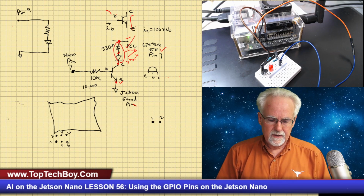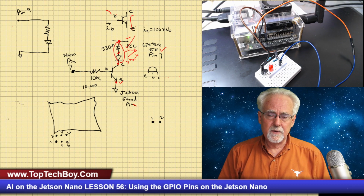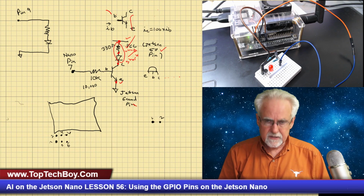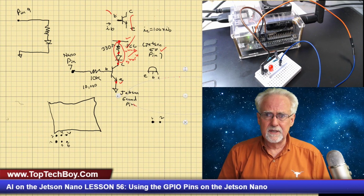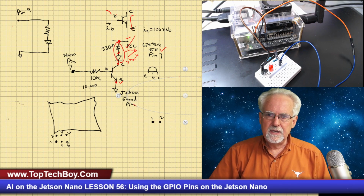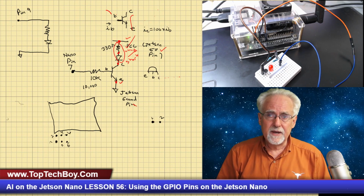So where are we going in the future? Well, a couple of disappointments about the board. I'd mentioned several of them. A couple of other disappointments about the Jetson Nano is that on the Arduino you have those little squiggly pins for doing pulse width modulation. There are no little squiggly pins on the Jetson Nano. So I'm going to need to show you how to set up and use PWM, and we can sort of simulate our analog out using PWM once I show you how to do PWM on it.